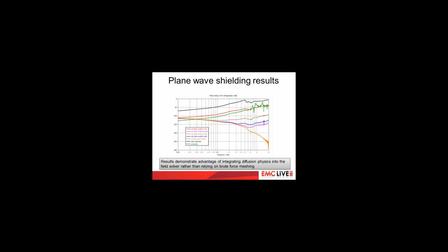Next, we cover the aperture with a metal plate using various interface materials between the cover and the dividing wall. First of all, we use a thin sheet of plexiglass, which is used to simulate a painted lap joint. This is the result shown by the green curve. Improved attenuation or shielding is seen at low frequencies, but this degrades at high frequencies, and some resonance behavior is observed. More about this in a moment.